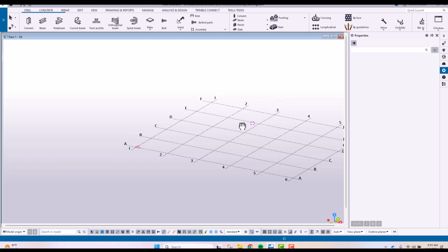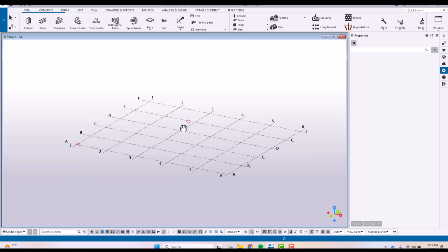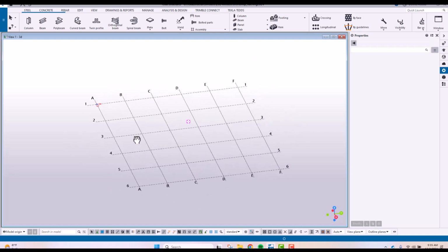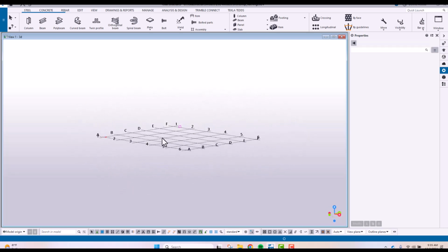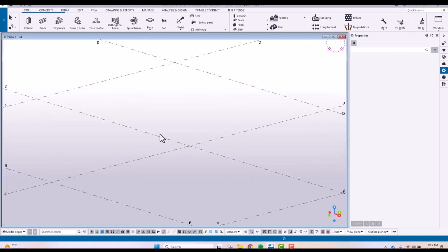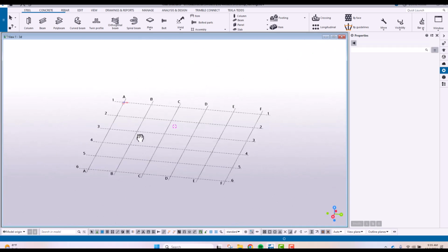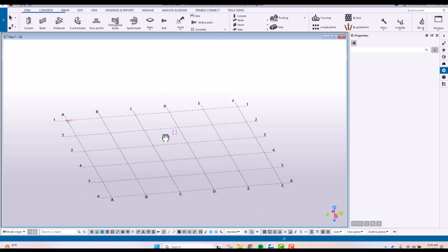Okay? Panning. Now if you want to rotate, I want you to press again the middle button of your mouse, press and hold. While holding, you press the Control key on your keyboard, and then move the mouse. That will be the rotation, okay? So that is the basic navigation of Tekla Structures: zoom in, zoom out, panning, and then rotation. And then Control P, changing the view.